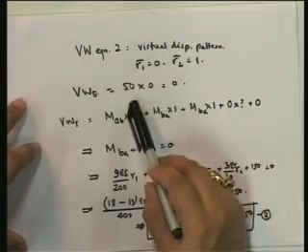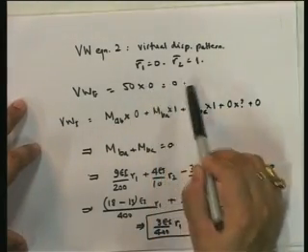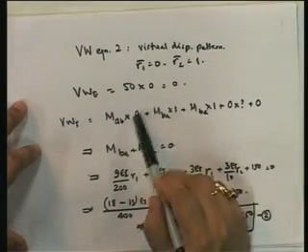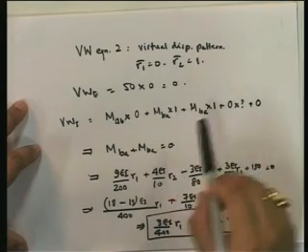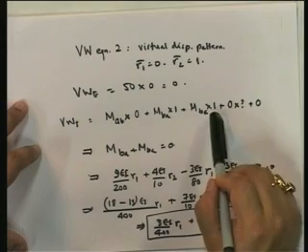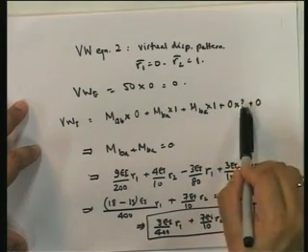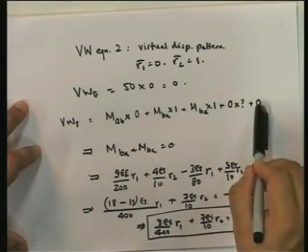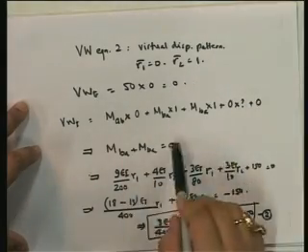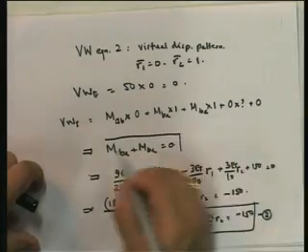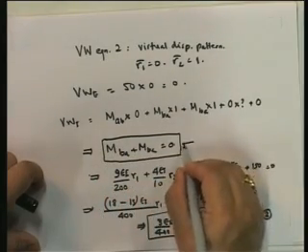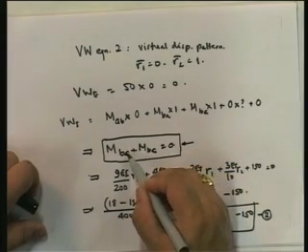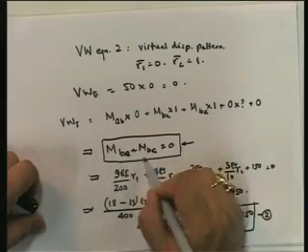So for R2 equal to 1, the 50 kilonewton does not undergo any displacement, so the external virtual work is equal to 0. Internal virtual work is MAB into theta AB, which is 0, MBA into theta BA, which is 1, MBC into theta BC, which is 1, plus 0 into we don't know what it is, but again 0 into anything is 0, so we don't care. And this is the work done by the 50 kilonewton because it does not undergo any displacement. So if you put this in, you get this equation, which is again, remember I told you that if you use the rotational kinematics, you essentially get back the equation that you would get by taking the equilibrium of joint B.